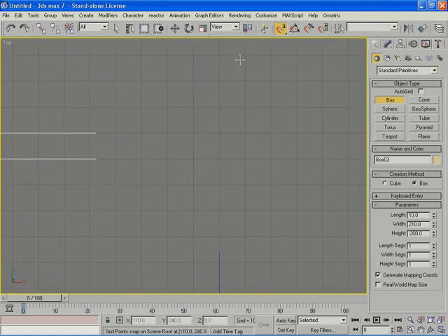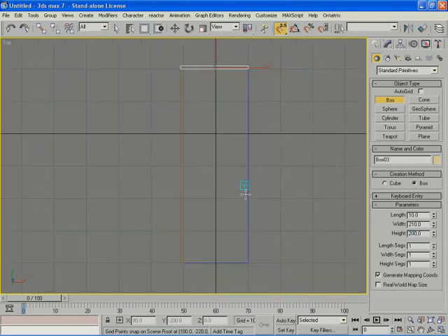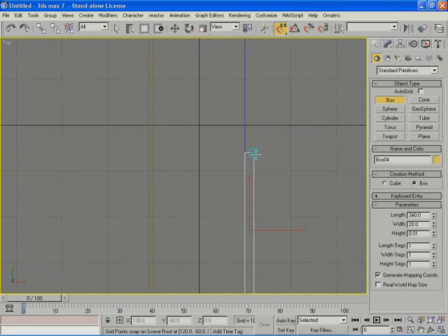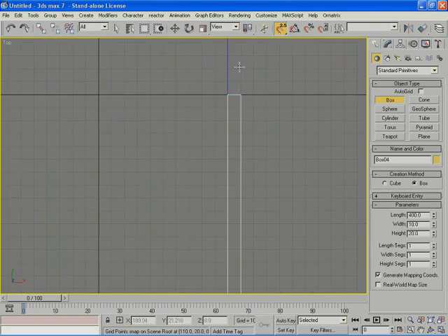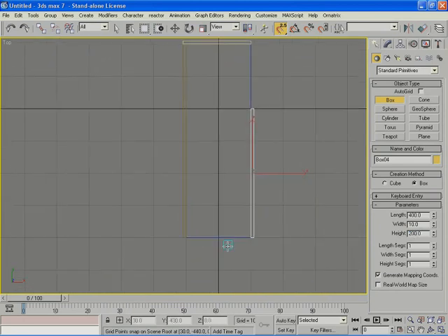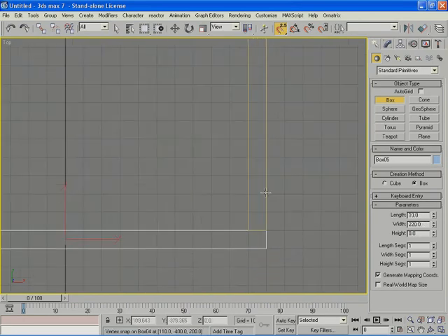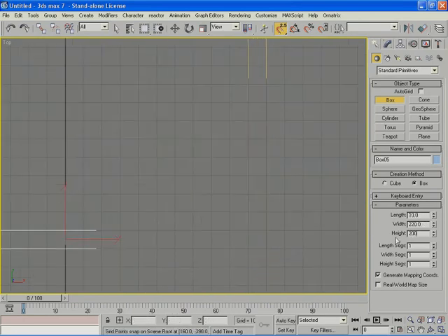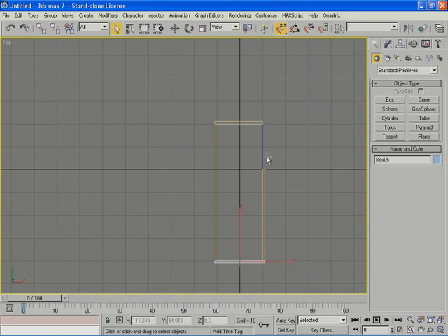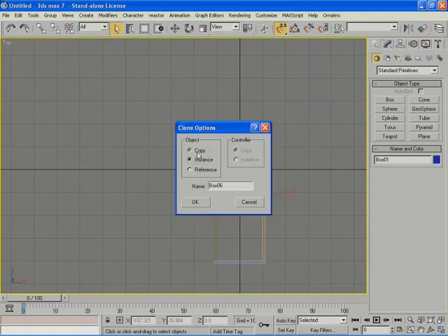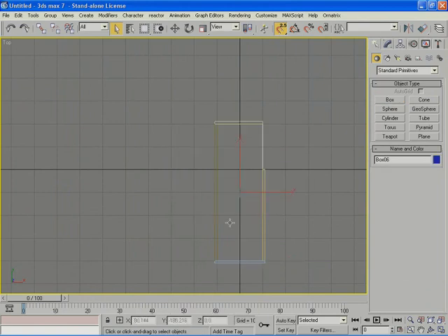And this is the back wall here. And I still need the ceiling. So copy the floor, go to a height of 200, and set the height to 10. So this is what I have so far. Light is going to come through this opening. I'm going to make the opening a bit narrower. So this is 500.